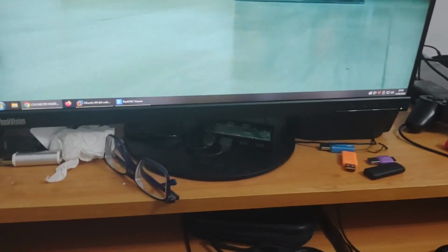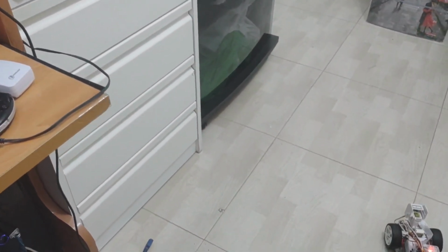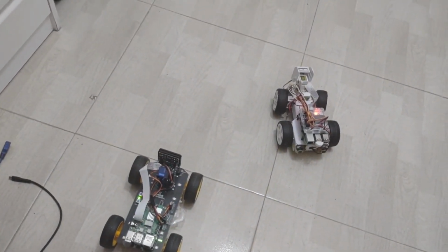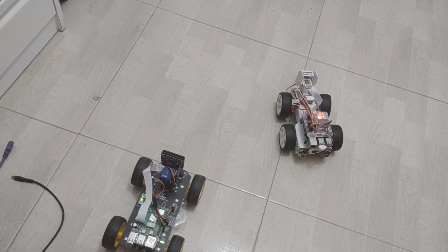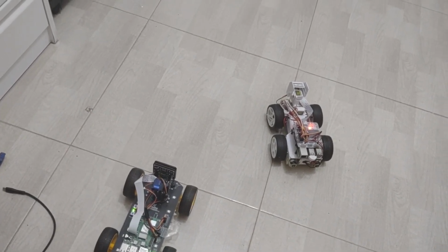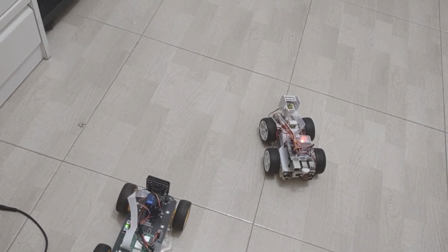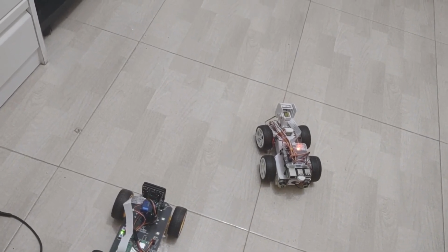Okay, more things. Logically, left and right: the wheels of this Sunfounder car turn 10 degrees each time you press. At first I put 5, but I have seen that with 10 it is better. In the assembly there was a small defect by which it was off center by 11 degrees, but I have solved it by software, in such a way that those 11 degrees have been corrected.